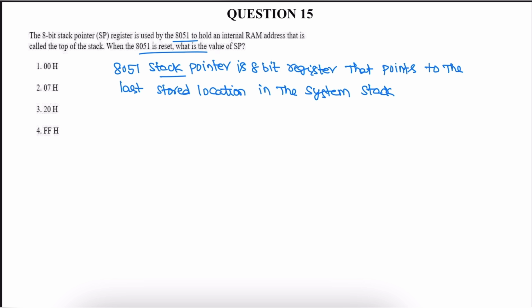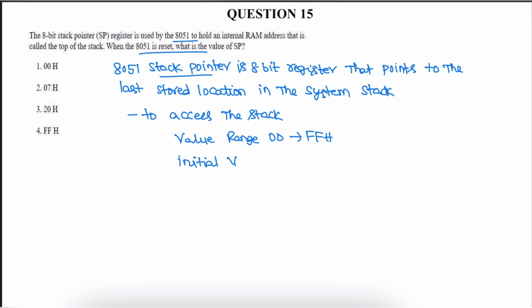So the stack pointer's purpose is to access the stack. Its value range is 00 to FFH, and the initial value is 07H when 8051 is powered on.